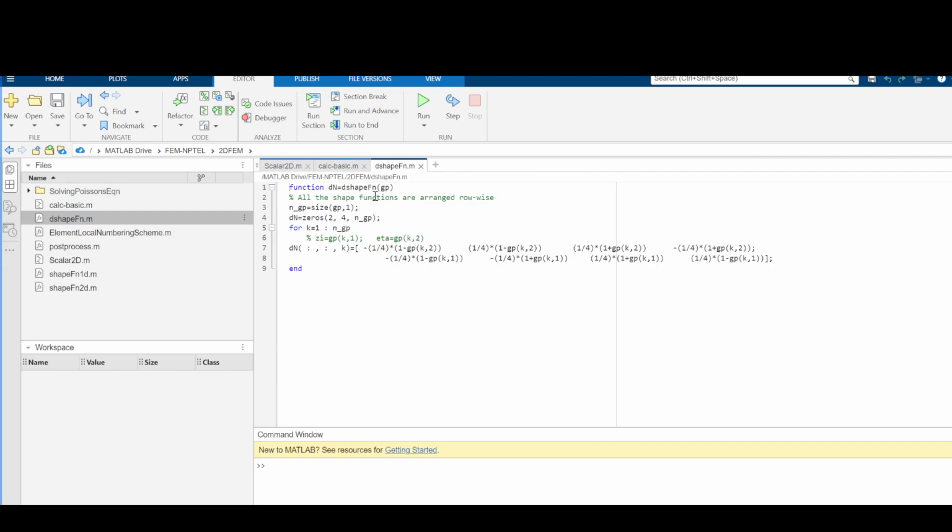This is the function that gives the output of the shape function dN, the gradient of the shape function. Suppose this is part of some integrand for a K matrix. In this case you are defining the derivative of this shape function here. So how will it calculate, because it doesn't know what the user is trying to do? It only gives output for dN.